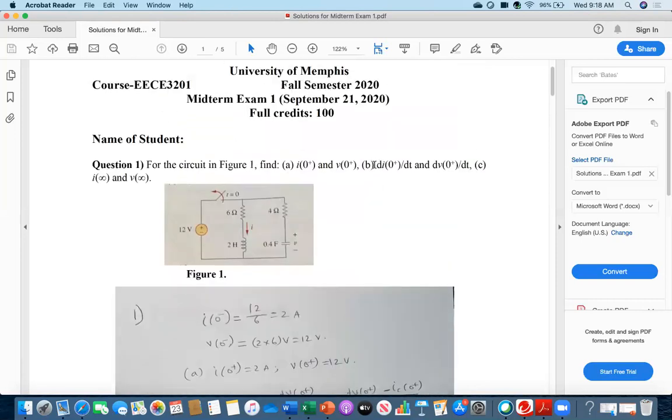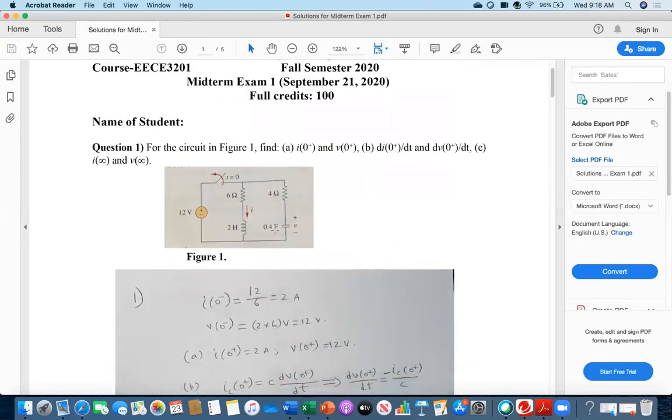So if I ever see a circuit that I know is going to go to 0, I can assume they're going to be negative? Yeah. For example, see, this is the current direction for this loop. So you can write plus, minus, then plus, minus. This will be the voltage drop. But then here it is minus, plus. It is given. So if it were plus, minus here, then it would be a plus sign there.